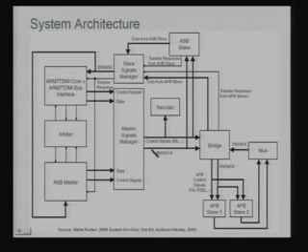The control signals communicate from the master to the bridge, and the whole idea is that the data which comes from here can go to any of these slaves. And this response, if you remember, there was a response signal flowing in. So the slave sends the response signal, and that response signal goes to the ARM core or to the other master.